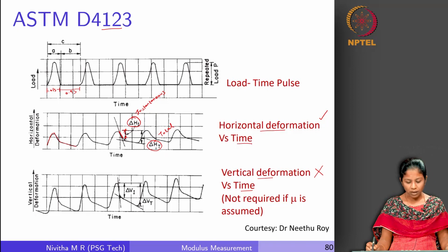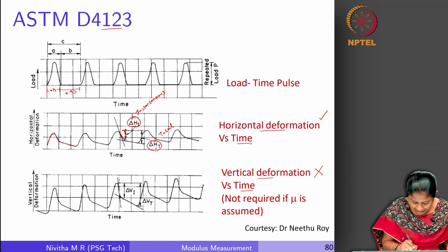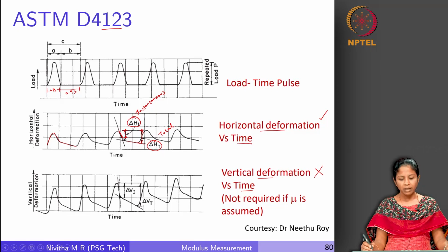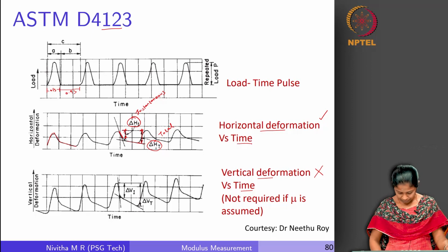Similarly, there is also the resilient deformation here, which is nothing but after the rest period is over, right, how much of a strain it is able to recover. So, this is indicated as the resilient deformation or the deformation that the material is able to recover completely. Using these two parameters, we will be computing the resilient modulus.